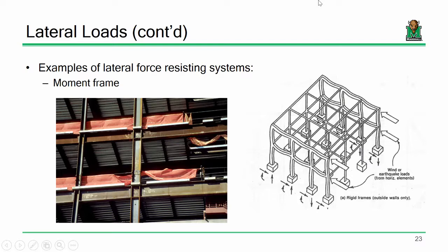The downside is that the actual beams and columns that go into these moment frames and the connections that are associated are a little more expensive. For instance, if you look right here on this image, you can see you've got these column lines and these beam lines. See how you've got these stiffener elements right here? That's an additional amount of welding and an additional amount of time that needs to be placed on the fabrication side.